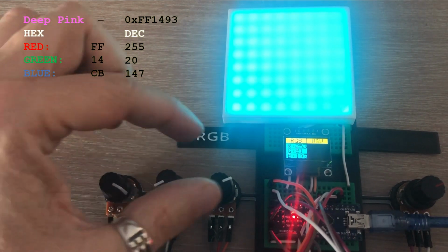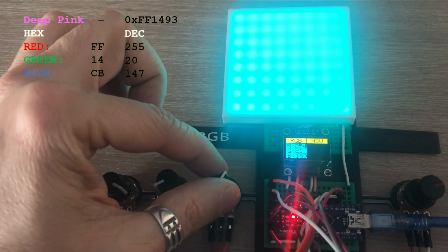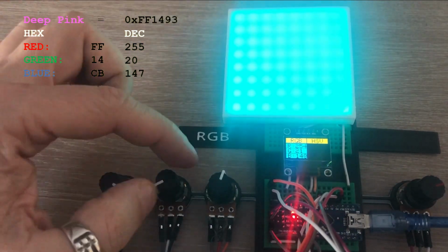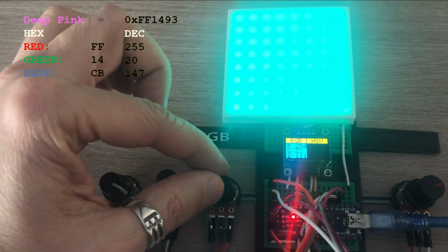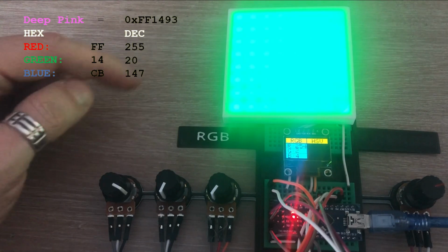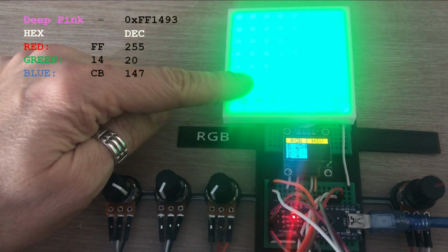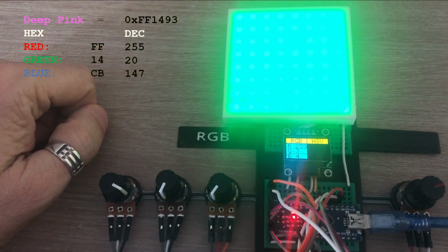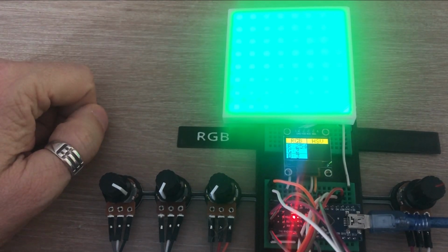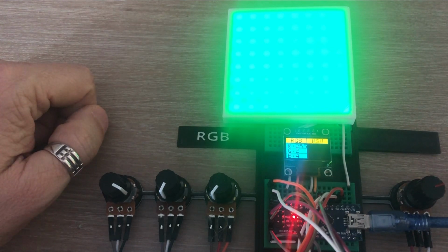I set the listed values for red, green and blue, and that does not look like pink. There is something wrong. Let's try to see if primary colors would work. And they don't. That color should be red, and it is green. So the LEDs I'm working with have a different color order. I did not realize that even with the same model of LED strip coming from 2 different manufacturers, wiring and thus color order may be different.